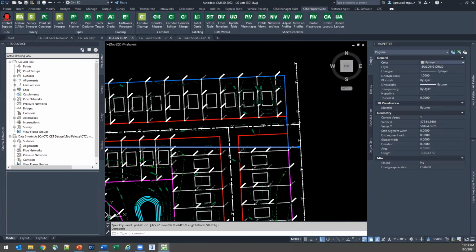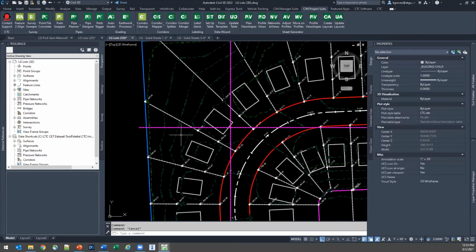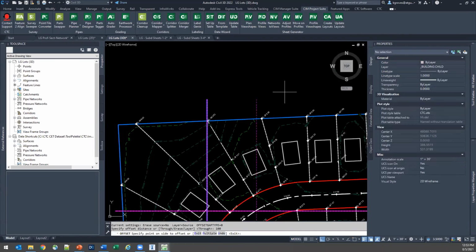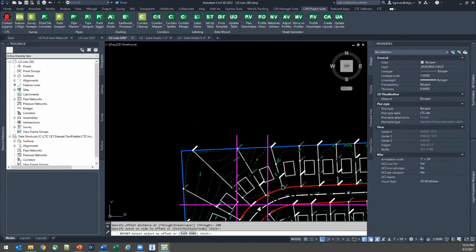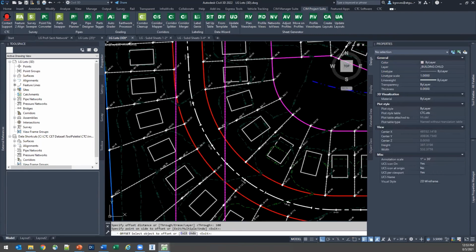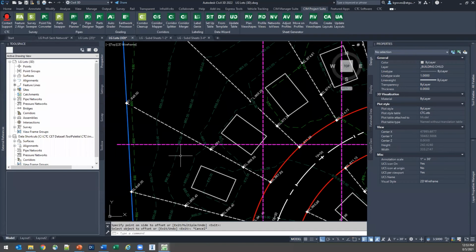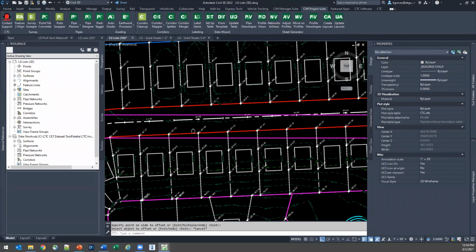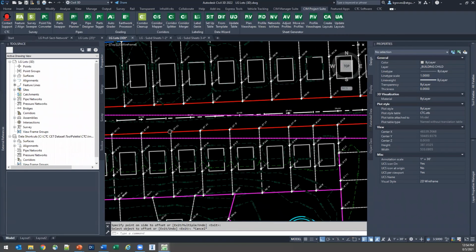If I offset these by 100, I'll see, hey, there's my every 100 feet on that vertical grid, yet my horizontal grid was set to every 50. So if I offset 50 in either direction, I should see a whole bunch of labels wherever that polyline crosses. Now, it is not doing one long multi-label line. It's inserting individuals with that single contour command.